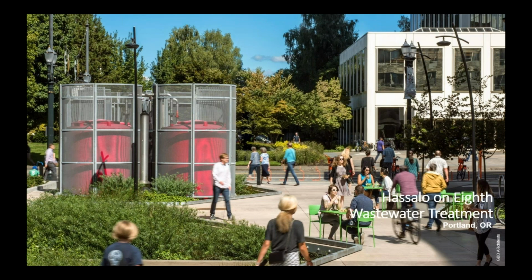There's a limit to that, where you look at infrastructure like the wastewater system for Detroit, Michigan, and I can badmouth them because I'm from there, so I have a license. That system is so massive, it takes almost a quarter of the state's population's wastewater, and they spend a ton of energy getting all this wastewater to a single point, and that's a costly endeavor. And if they wanted to treat it to reuse quality and send it back to everyone, it would take an enormous amount of energy and infrastructure to do that. So the closer you can be to where water is generated and where you can treat and reuse it, the better, and that certainly changes the economy of scale.